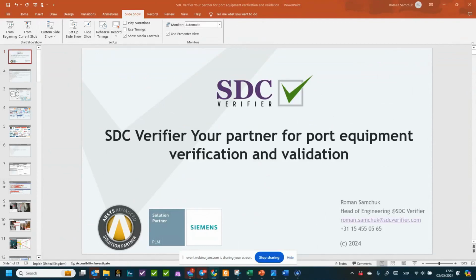Is it possible to simulate non-continuous welding on stiffeners? Yes, of course, because basically that is coming down to your modeling approach. So if you model your stiffeners as non-continuous welding, then it's fine. Yeah, you can do basically having stiffeners directly modeled. There are several possibilities. So you can conduct directly the stiffener check and also local fatigue check close to the welded details.